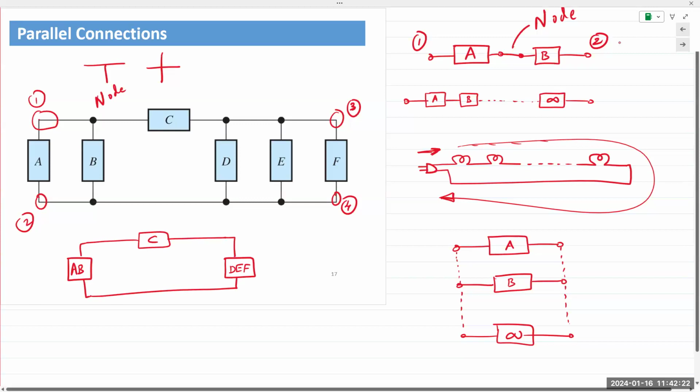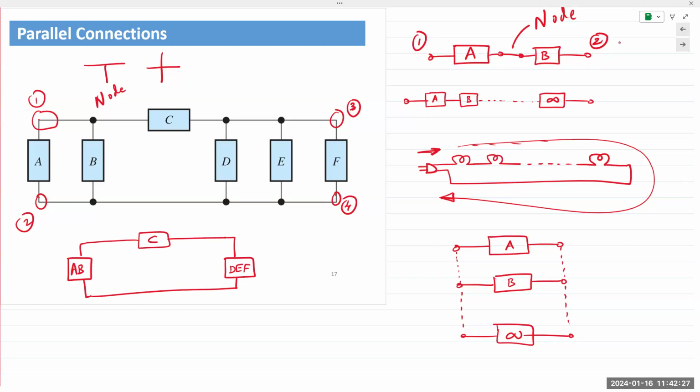Now, what can we say about C relative to the rest of the elements? They're all in series, right? Most common mistake happens right here because you have 3 connections here, 3 connections here, and 4 here and 4 here. If it's not quite obvious, you would say, how can they be in series and in parallel? That is true. The relationship between A and C and between B and C, or C and any element so far, is nothing. It's not in series and it's not in parallel.